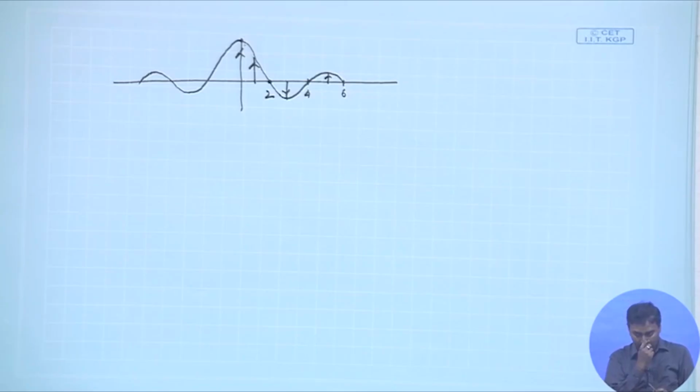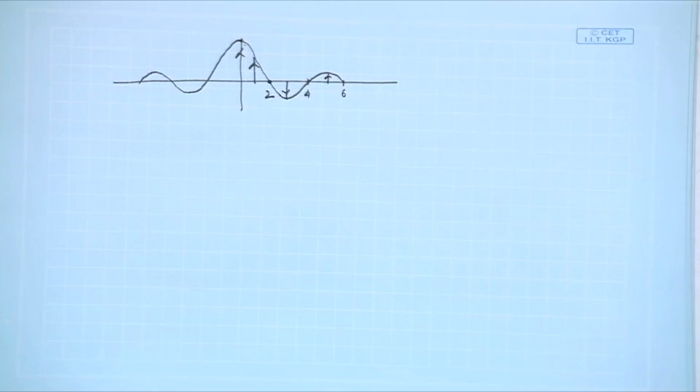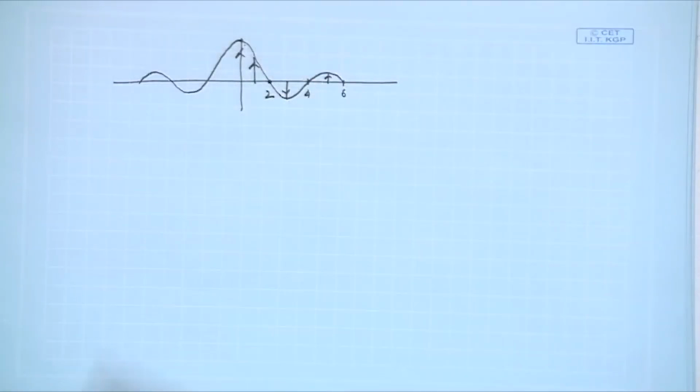Okay. So, this is the plot we get, d0 and the corresponding dn. Do we have a phase over here? We do not, because you have seen that all the dn are no longer complex. So, they are all real values. Basically the phase plot will be all 0, it does not have any phase plot, just an amplitude plot. What eventually is happening is that these sinusoids are getting mixed.